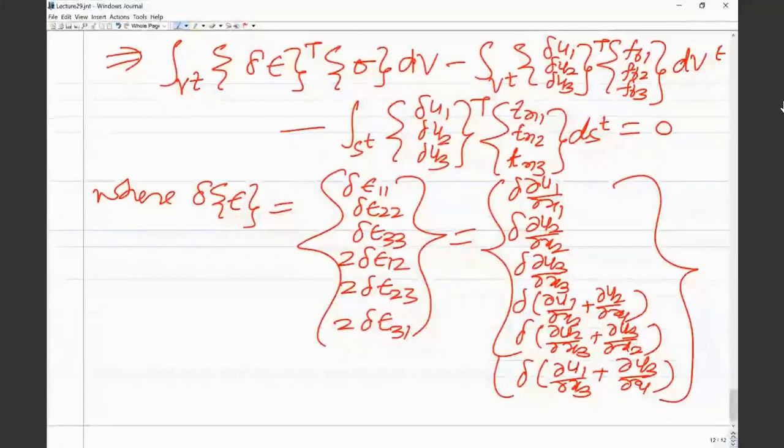So you would see that in the current configuration, in the weak form, we are getting neither the Green-Lagrange strain tensor nor the Eulerian-Almansi strain tensor, but we are getting these linear terms over here, and this is exact as it is coming from the weighted residual statement and then the weak form.